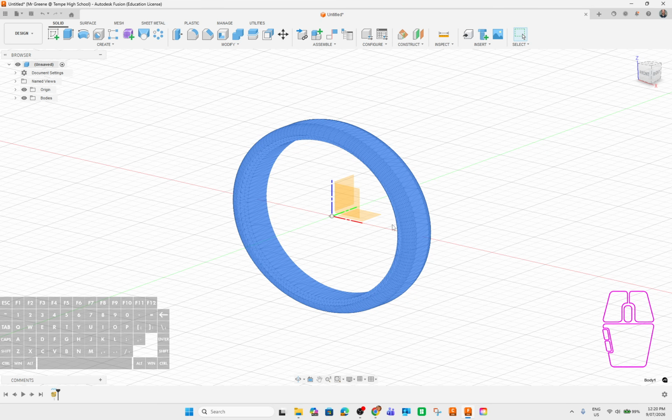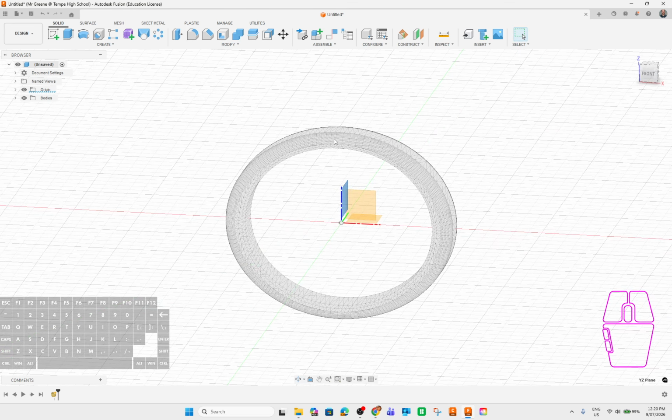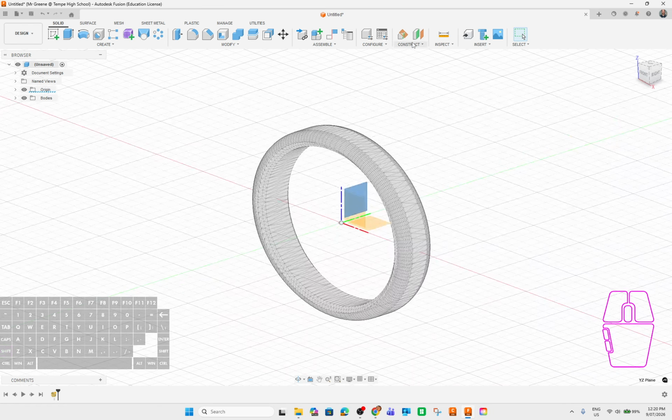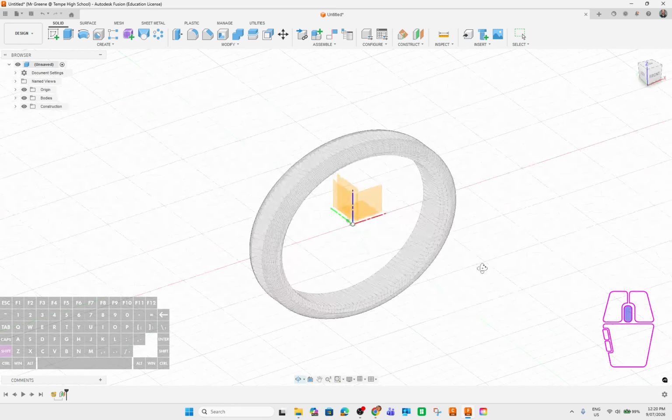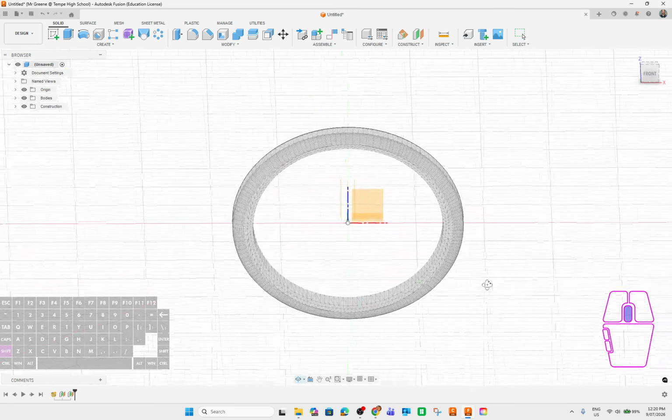Yeah. So first thing I want to do is select a reference plane, and if I'm cutting out a 5mm strip, I want it 5mm spaced around the middle here. So I've got to divide 5 by 2. So I need a 2.5mm offset plane on either side. So I'll select the plane I want to use to cut, and I'll offset that by 2.5. Then I'll do another one over here, offset plane. This will be a negative 2.5 in the negative direction, and fantastic.